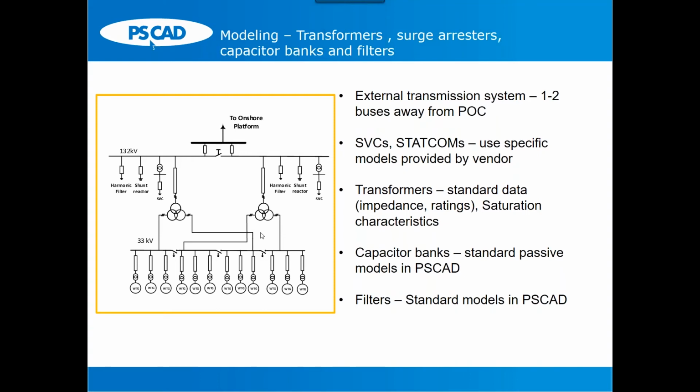Then if you have SVCs, STATCOMs, or similar devices, synchronous condensers, you have to model them, because in some cases, when you have a transmission system fault and isolate the transmission line from here, maybe the STATCOMs can help mitigate the overvoltage or TOV.